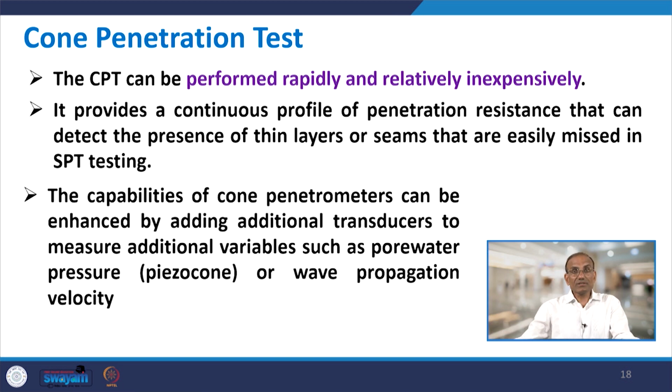It provides a continuous profile of penetration resistance that can detect the presence of thin layers of sand that are easily missed in SPT testing. The capabilities of cone penetrometers can be enhanced by adding additional transducers to measure additional variables such as pore water pressure, piezo cone, or wave propagation velocity. So, this can be done.